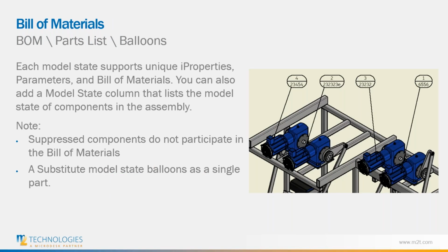Now, these instance properties also can be seen at the drawing level, okay? You could see them in the bill of materials, in the parts list, in the balloons. Now, typically to get these to show, you are going to have to make some modifications to things like the styles library. So if you want to see a unique property, a serial number per se, okay?